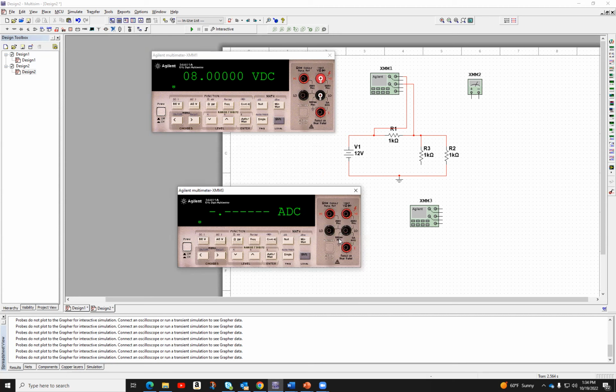So again, I have to use these two button connections to have the current that I want. So I'm going to hook up my resistance here, and I'm going to hook up the other side of the resistance to here. And now, as you can see, these two are connected in series with this resistor, and these two connections are in parallel with this connection here, right?